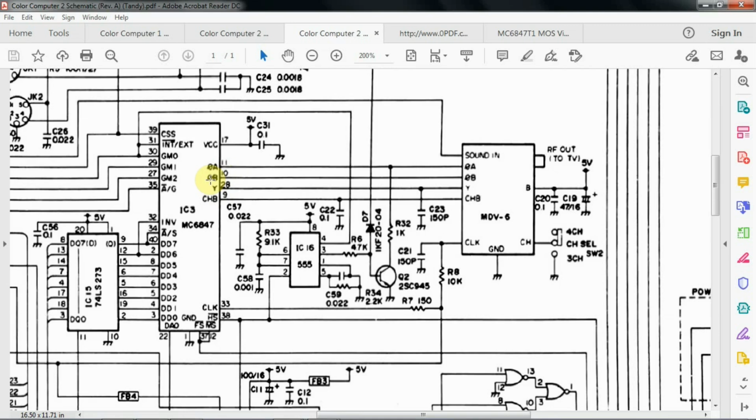So where RGB was 3 signals with separate lines for synchronization, S-Video is two signals only. One signal is the Y, or the luminance, and it also contains the synchronization information. So you get your vertical sync and horizontal sync pulses embedded in the Y. And then the second signal in S-Video is chrominance, and it's a combination of the phase A color and the phase B color. So these signals go over to the RF modulator box into the 1372.